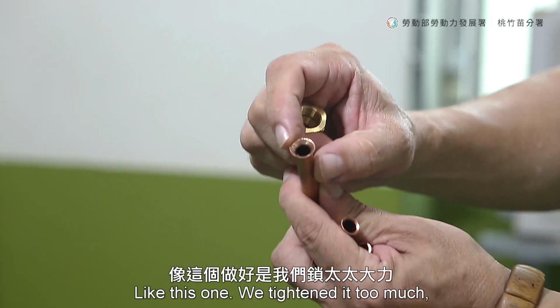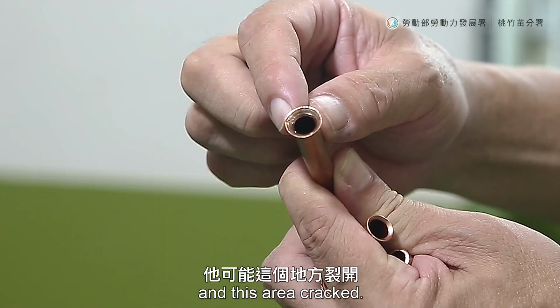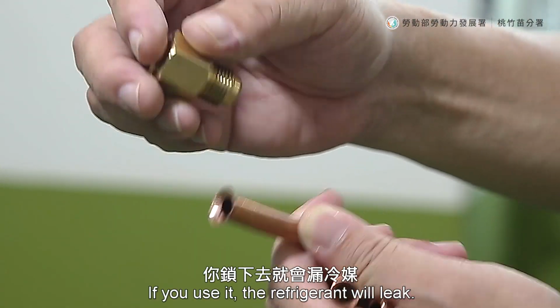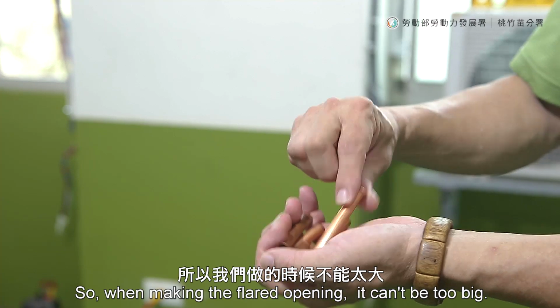Like this one, we tightened it too much, and this area cracked. In this case, this opening should not be used anymore. If you use it, the refrigerant will leak. So when you make the flare opening, it can't be too big.